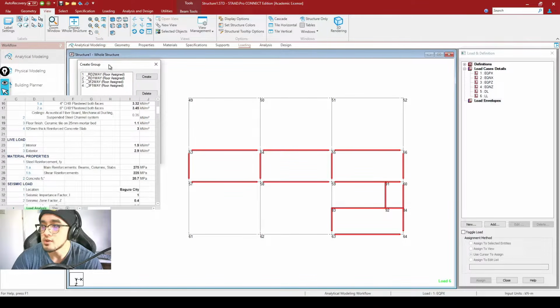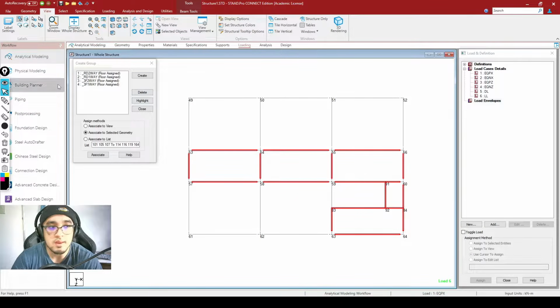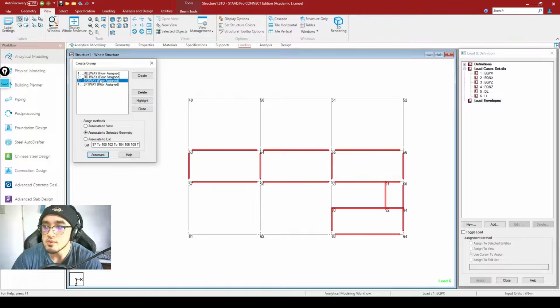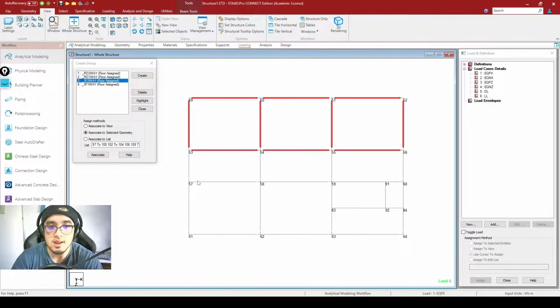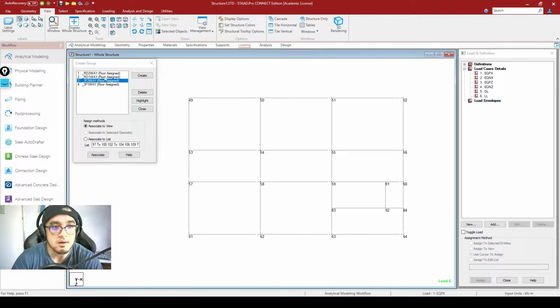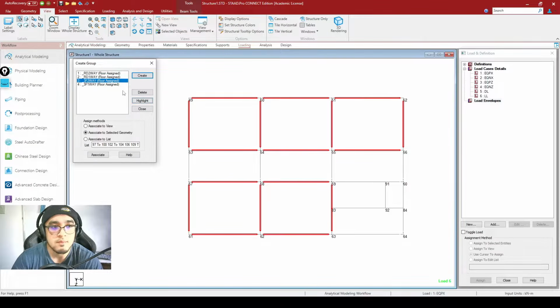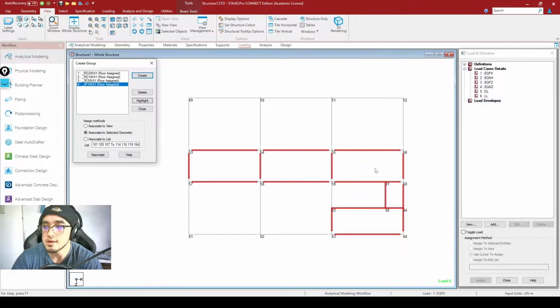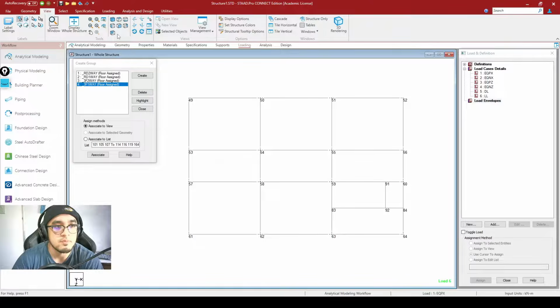I'm not quite sure if you saw, because I just noticed now that my Excel file is in the way. So I would be hiding it first. So there. Once again, I assigned this one right here to the two-way slabs. So I selected them here. So I selected this one here. And I assigned this one here to these slabs right here. So that is for our third floor.